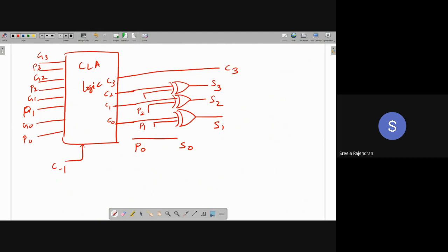Delay of each gate: you see, all gates do not have the same delay. This is just for understanding the concept of delay, that I have said that XOR has more delay than AND gate or OR gate. But we are just trying to understand what is propagation delay, so here we are not bothered. In many applications, when we study for theoretical purposes, we assume that all the gates have a nominal delay which is equal, like unit delay. I say one unit of delay for each gate.